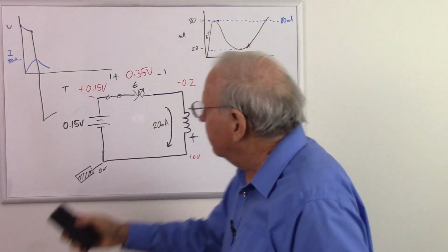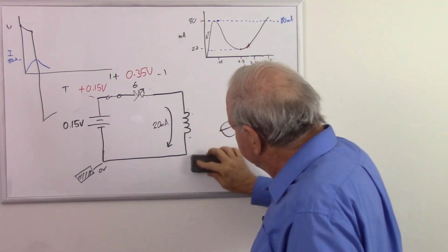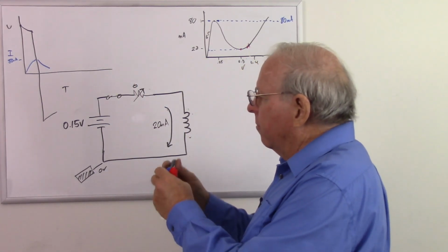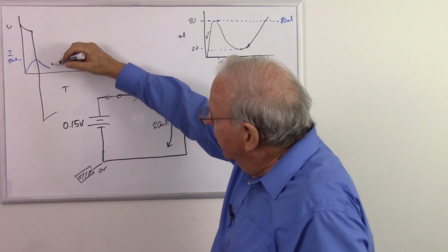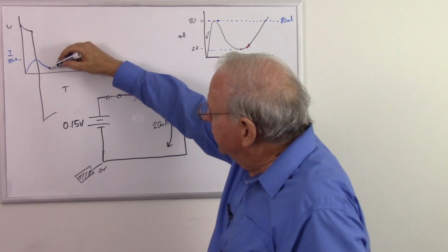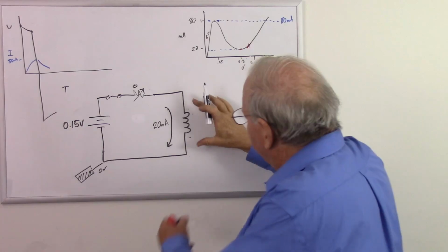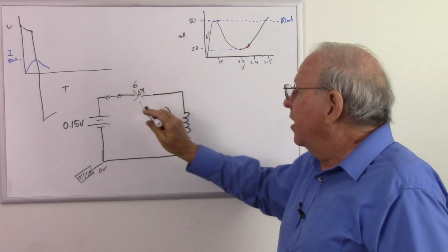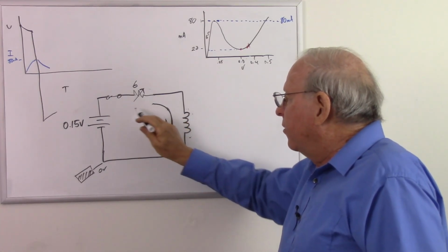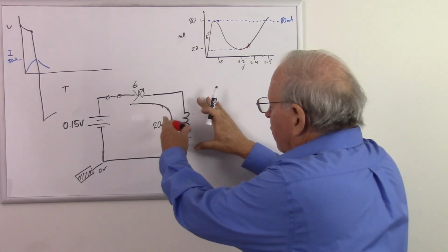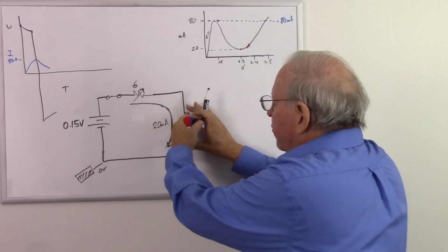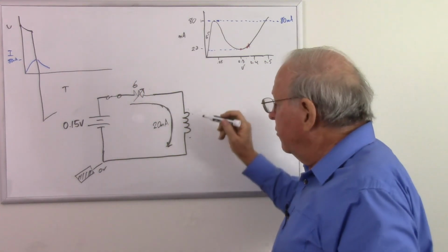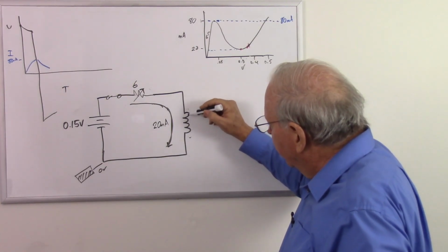Let's take all these numbers away because they're no longer relevant. And so now we are back to this point here. Our current has dropped down to about 20 milliamps. Our voltage has dropped down across here appropriately. This is suddenly going to go down to a very low resistance, causing the current to start flowing that way. Now it's being pushed this way. This no longer has the energy it had, and so it's going to suddenly reverse. So now instead of it creating current, current is going into it. It becomes a consumer again, so current is flowing into it.